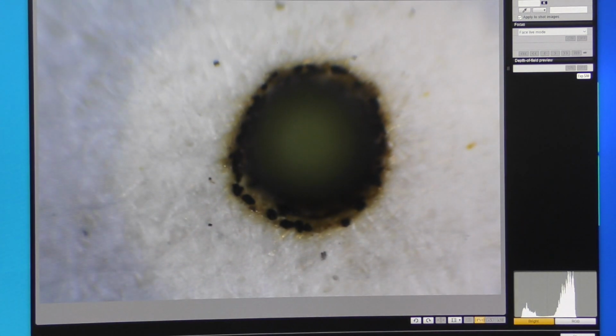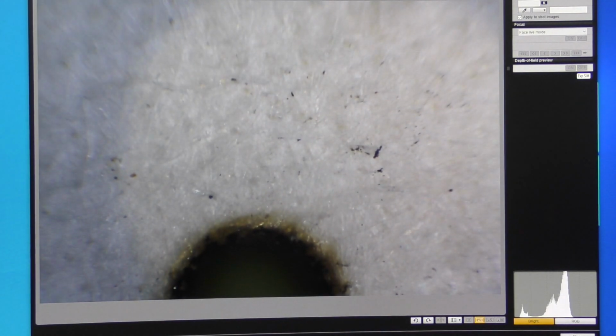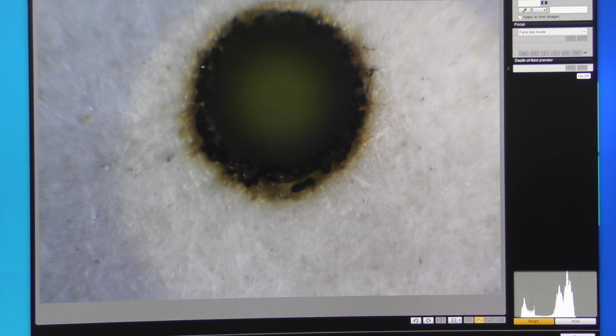And you'll notice that although the hole is getting bigger, the actual halo around the outside is getting a little bit tighter, a little bit better. And then we get to 63.5, which is the focal distance. At that point, the hole size and the halo virtually match. So you could say, well, that's the focal point, because most of the energy is passing through a single point. And if that's the definition of what a focal point is, then is about 0.7.